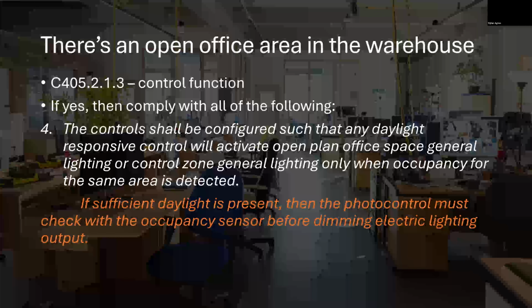And then for daylight, basically daylight has to check with the occupancy sensor. So say there's sufficient daylight in the area, but then a cloud happens and there's not sufficient daylight. So then the sensor would read, hey, we need to turn the lights on to meet the illumination threshold level. It needs to check with the occupancy sensor first to say, hey, is there occupancy in this area? If yes, then okay, raise lights. If no, then stand by. So just applying a logic tree for the control functions, that's all.